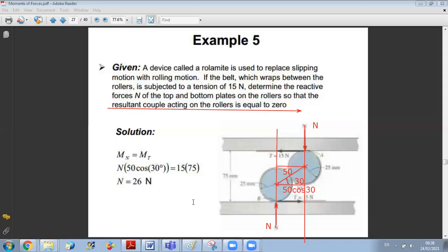Excuse me, isn't the perpendicular distance equal to R or no? No, it's not the perpendicular distance to R because for it to be perpendicular, you should have a right angle between the normal line and the line joining the centers. But it's not a 90 degrees angle. This one, okay? It's not 90. It's equal to 60 degrees because here you have 30. Okay, here you have 90. So since the angle between this line and the normal line is not 90, you need to do the projection.